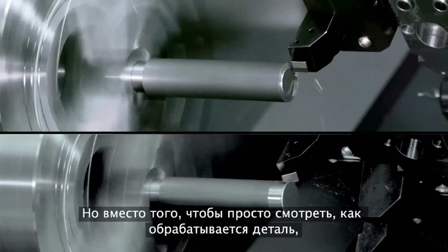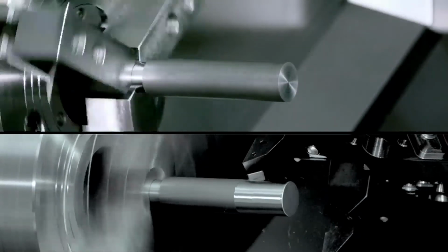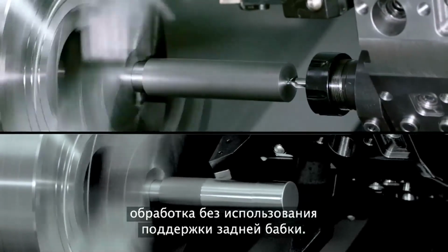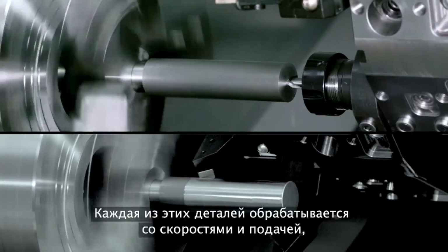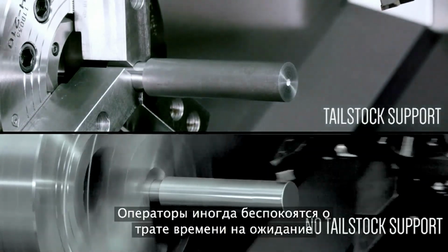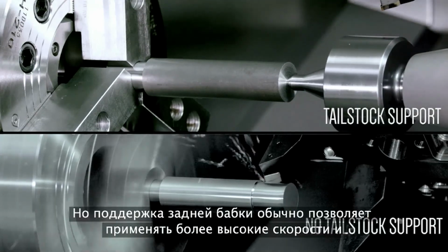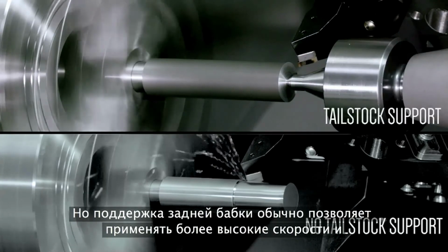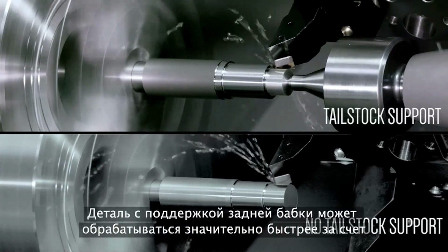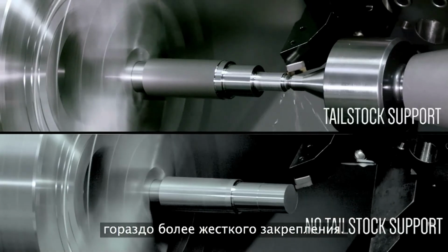But instead of just watching this part run with the tailstock supporting it, we thought it'd be a good idea to watch how it performs running alongside a separate run made without the benefit of tailstock support. Each of these parts are running with speeds and feeds optimized for the amount of support available. Machinists sometimes worry that they'll lose time waiting for the tailstock to clamp their part, but tailstock support usually allows higher speeds and better finishes. The tailstock supported part is able to run considerably faster since it is held in a much more rigid state.